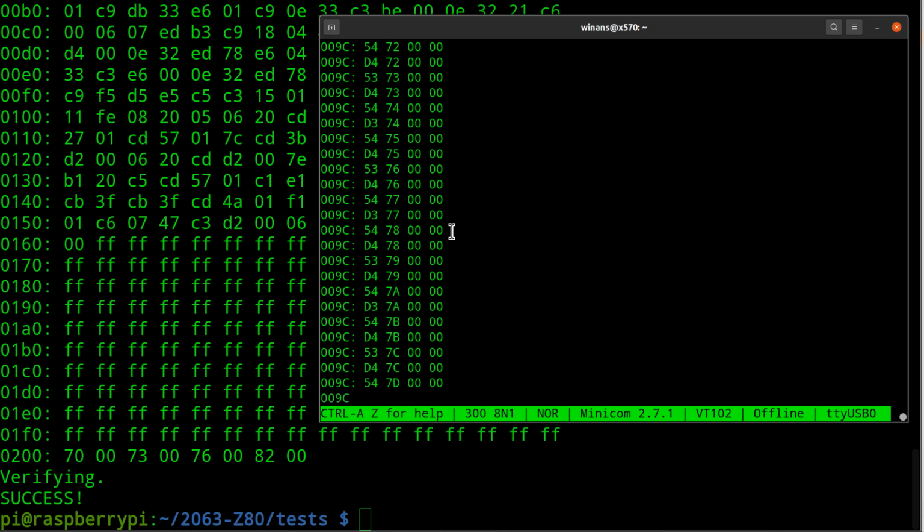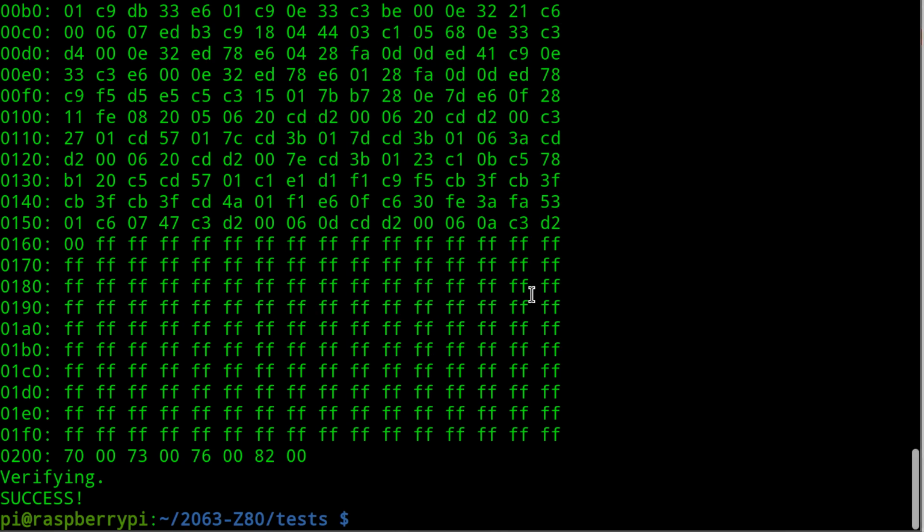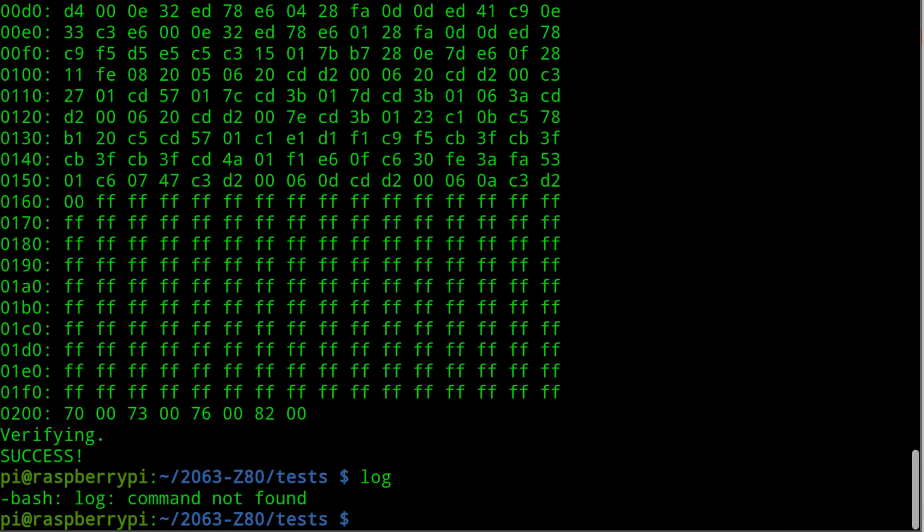This is what you get into when you're dealing with interrupt handling if you're not thinking about timing in what we call critical regions of code. So I'm way over time in this video. This is actually a two-parter and one big wide. But let's go ahead and banter a little bit and see what we can do about this, because if it really is taking this long, even if it runs at 115.2, this could happen from time to time just because you may not be halting or you're doing something else that consumes a little bit of time before you get back to waiting again, right? So as I said before, the idea that you'd put a halt in there and somehow that would fix your code is foolishness.